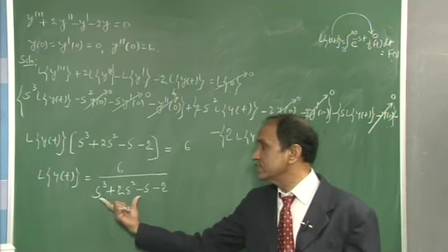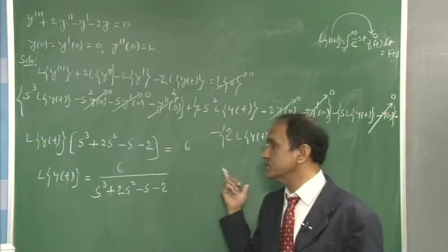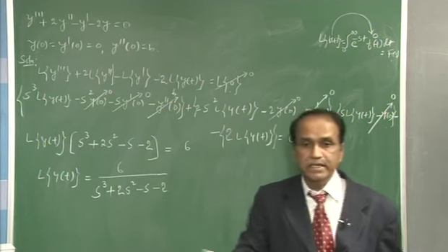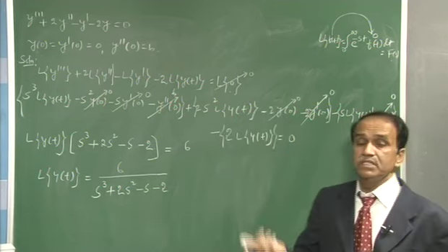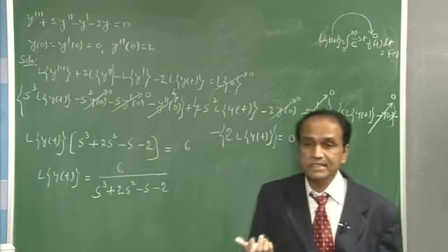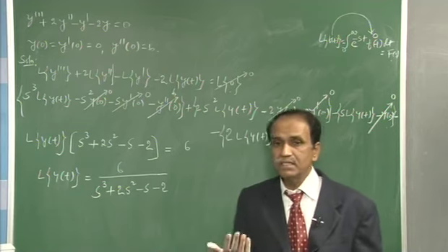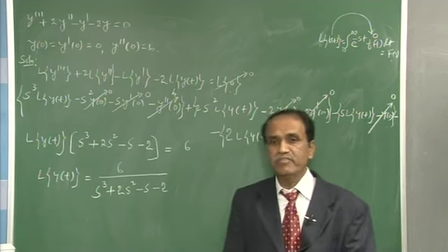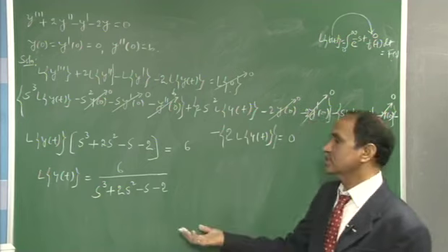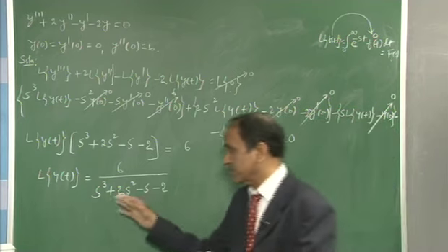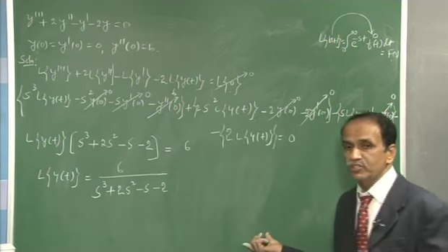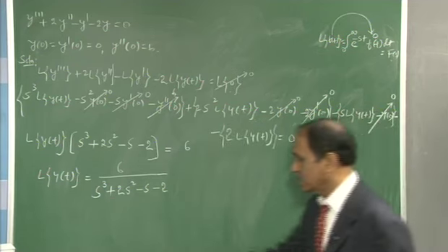Then you have to define this total quantity as a function of some s, then go on giving some trial values like s equal to 0. For whichever value the equation is satisfied, that itself will become one of the factors. Then divide that total function by the first factor, and the remainder you take will act as another coefficient.